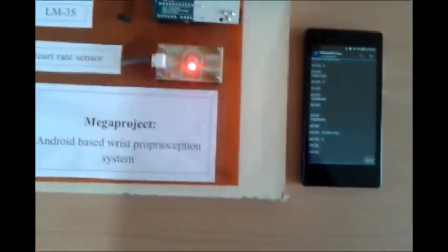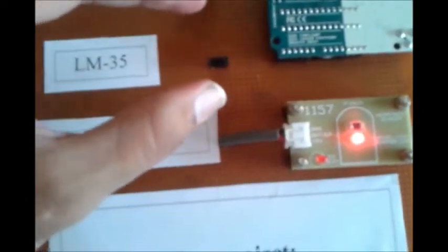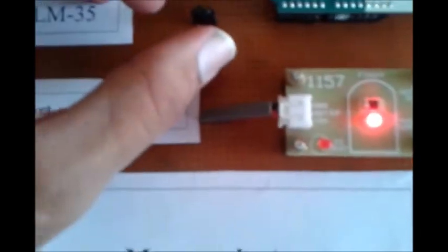Okay, so let us check whether it works if I change the temperature. Let me connect the device first with HC05. Okay, the connection has been established. Now I am putting my finger on the LM35 and we can see the temperature is increasing. It has increased to 33 from 32, where 32 was the earlier temperature. For now it is showing 32, 33, 33 and a continuous output of 33.